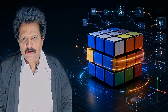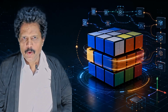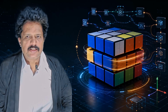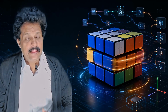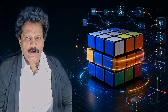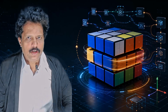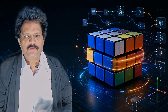In the first part, we created the basic Rubik Cube structure procedurally. We used a cube node, instance on points, smaller cube pieces, face index values, position comparison and rotate instances to rotate only one selected layer. But we also discovered an important problem. When we rotate one axis first and then try to rotate another axis, the rotation logic starts breaking. This happens because a simple rotation setup does not properly remember the previous state of the cube pieces.